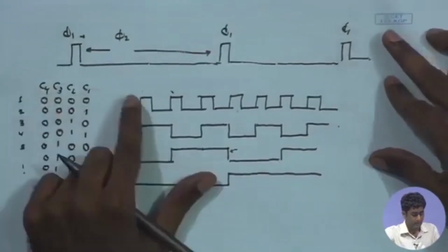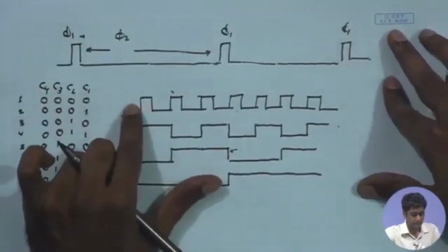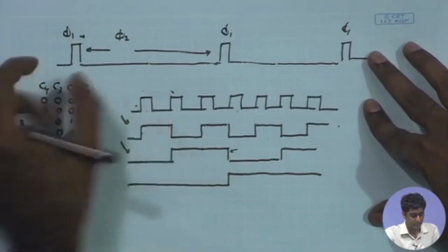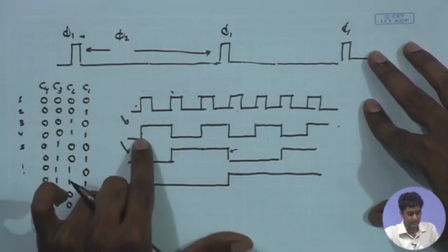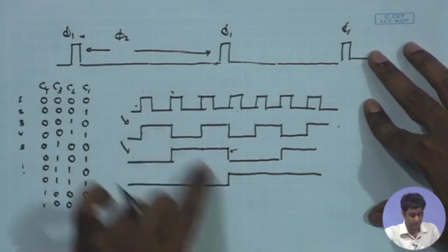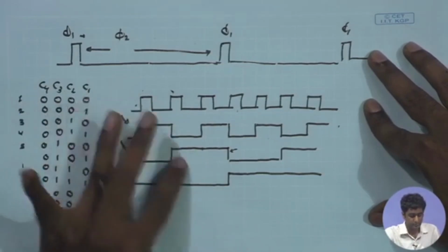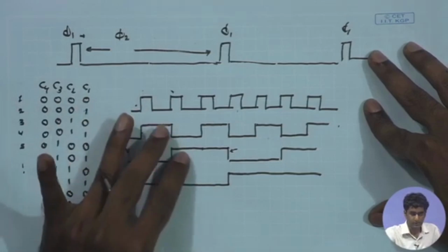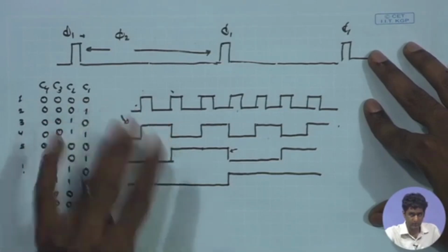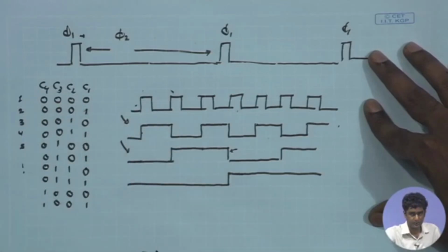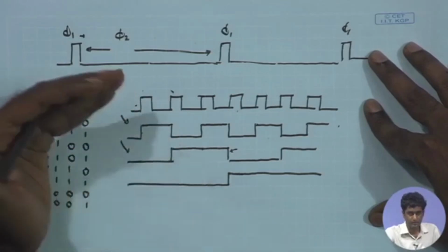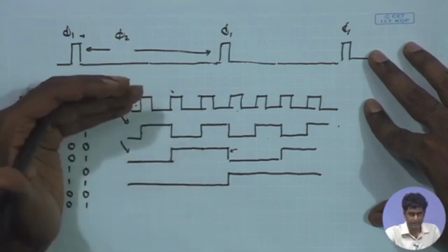The other important consideration is that the overall operation of each of these bits is going to be edge triggered. So, the transition happens at the edges of the previous clock or the previous phase. So, we need to look at the edge triggered operation, and therefore, we are going to look at the flip flop. Sequential circuits which give us clock driven operation can be level sensitive or edge sensitive.